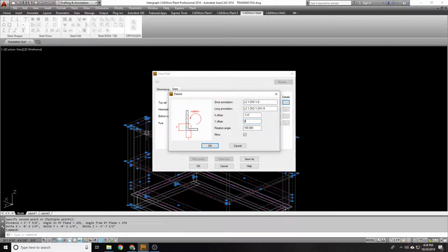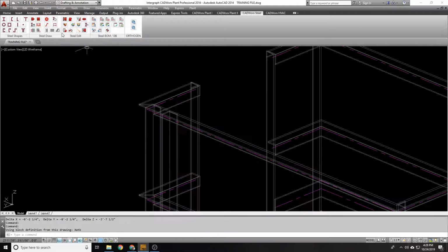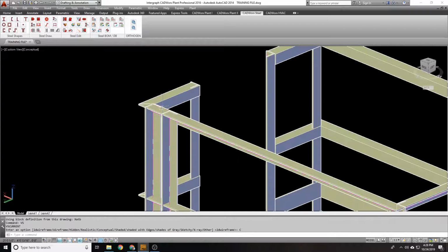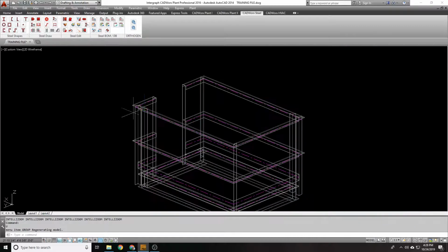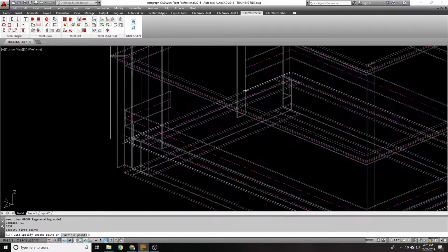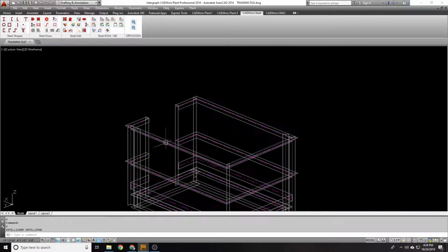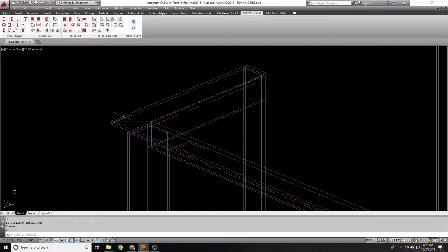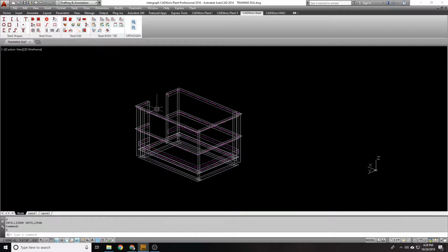Had it not gotten that 1/4 inch Y offset, it gets brought down 1/4 of an inch, and you'll see the post kind of sticking through because now this is in the same plane, right? And so now when we measure, we will get that 3'7" and 1/4. But because we had that 1/4 inch offset in the Y-axis for this top post, it pushes it up 1/4, and we get that extra 1/4 inch added to it. So, all right, so there's that.